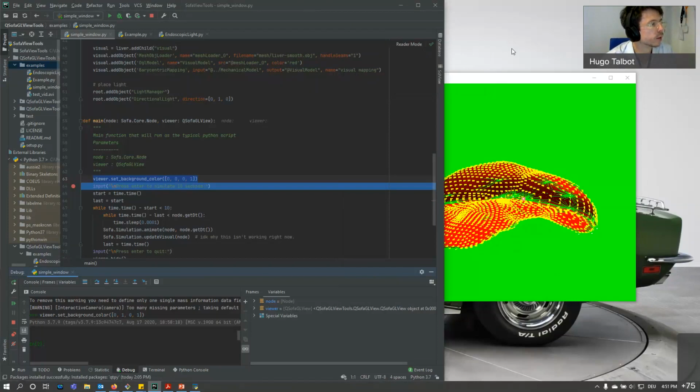Yeah, no, we basically implemented it as, I guess you could kind of see it as damping, essentially sucking energy out of the system, or slowly dragging the positional states down. Then we had a zero cutoff, so some constraints, I forget what the stopper constraint in SOFA is, for all the nodes to make sure they didn't drop below zero.